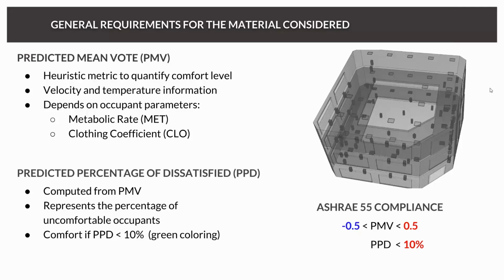And also the PMV says that you need to include into your calculations the metabolic heat released by the occupants, and also the insulation level of the clothing. So this PMV is, at the end of the day, an artificial temperature or something related to temperature that would tell us if for the majority of people these conditions would be uncomfortable or comfortable.